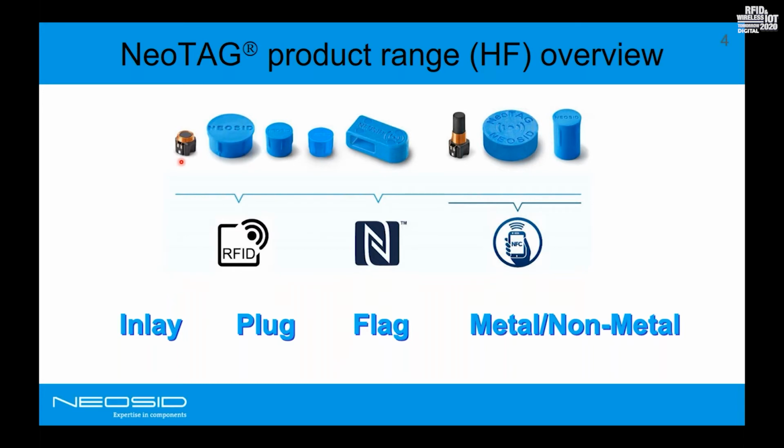We have a special ferrite core and a small RFID IC is placed on it, and we wind directly on the ferrite core to build up the antenna for the RFID tag. We call this type of transponder an inlay. Another version is the long inlay, where you can get bigger reading distances. This inlay is used for different other shapes of transponders in our product range.